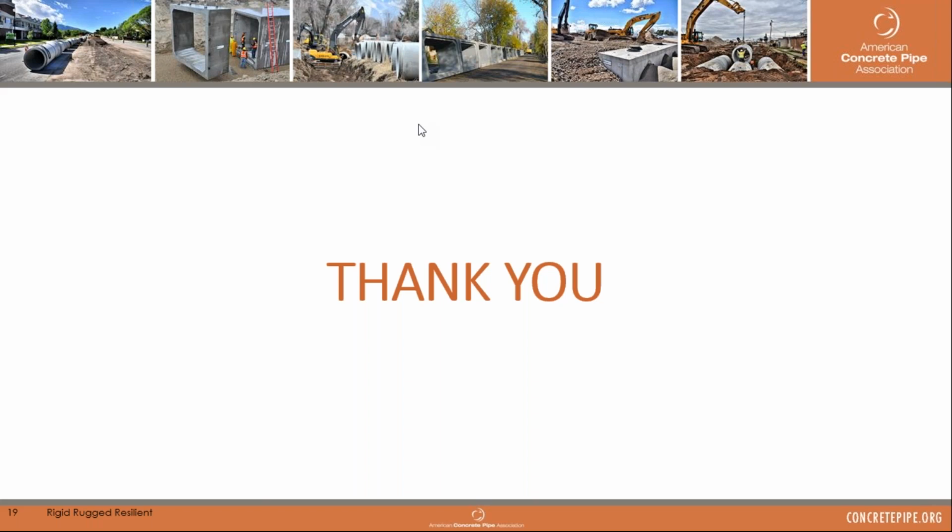Because if you're going to anticipate that there's a lot of deflection right at that structure, you should probably be using some kind of flexible connector, either a water stopper, or we recommend using flexible rubber boots. So I hope that answers it. I guess from a design perspective, it really just comes down to you might need to use a different set of assumptions if you're trying to control those deflections and those stresses at those different locations.